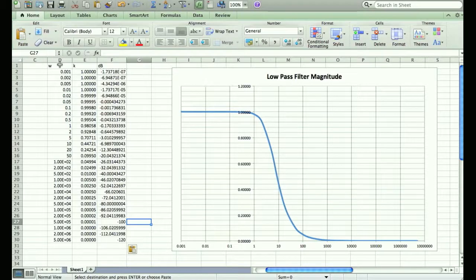So when you take a log base 10, a gain of 1, right? Output equals input, and that's a gain of 1. That corresponds to 0 dB. 0 dB is like 0 change. There's no change between output and input, 0 dB. So I'm going to copy and paste that down. What was that formula again? 20 times log base 10 of your magnitude.